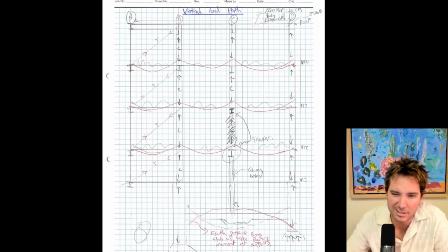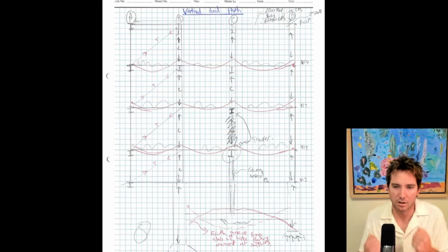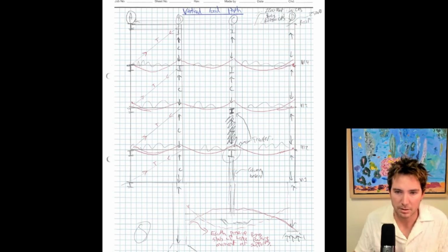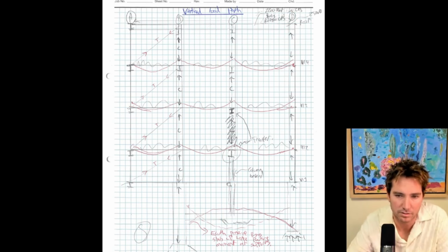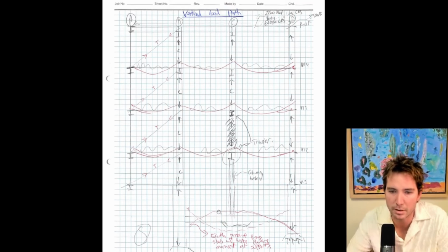I've got the bending moment going in 2 directions because if the D walls sink, the earth pressure will push up and you'll get that reverse bending moment diagram. But also, depending on the loading on that column, when it pushes down, that will also act somewhat as a suspended slab, where the D walls are supporting my base slab and that point load coming down is pushing in. So that's kind of why I have the 2 bending moment profiles there.